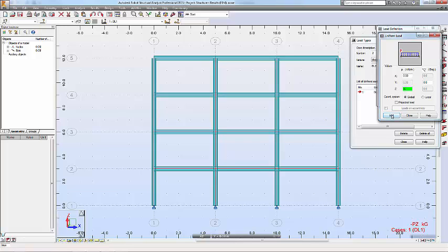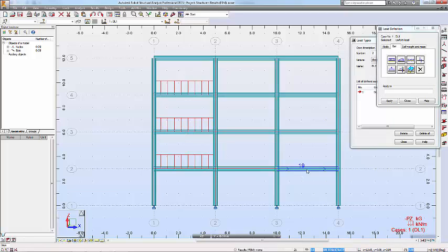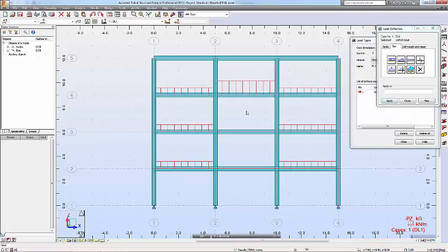Once we finish, we click on add, and then when you move your cursor back, this becomes applying mode. So we just pick the bin, use the tip to pick the bin, and then you can apply the loading on. So that's 5 kilonewton per meter for this section. And then the other one is 10 kilonewton per meter. So what we need to do is a -10 kilonewton per meter, just add to it. So we can add to this one.